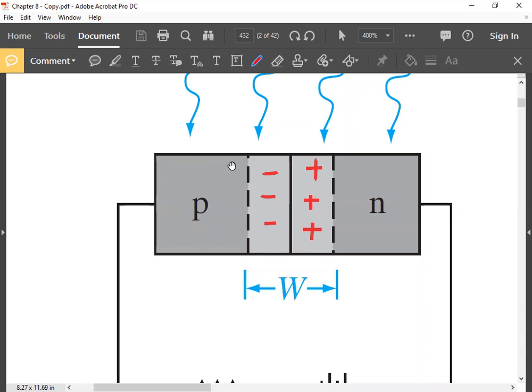Okay. Yes, sir. So within one diffusion length, the carriers which are generated may go to this depletion layer, but the carriers generated further away from this edge will not be able to diffuse here. Okay, so we will not consider those electrons. Similarly here, from XNO within one diffusion length, the diffusion length for holes, of course, not electrons.